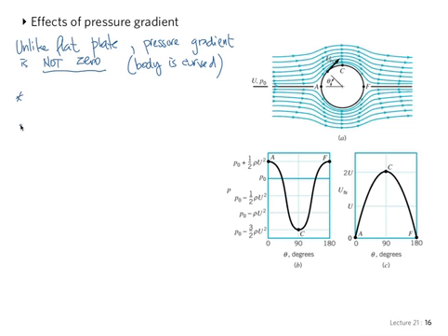if you recall this discussion that outside the boundary layer, the flow was behaving as if it was inviscid. So in this case, because of the curved streamlines, the free stream velocity is changing and the pressure is changing according to Bernoulli's equation, and all of that pressure change extends all the way inside to the boundary layer. And so to discuss this a little bit more, consider the flow around the cylinder, and in the completely inviscid case, right? There's no boundary layer, nothing, the completely inviscid case.